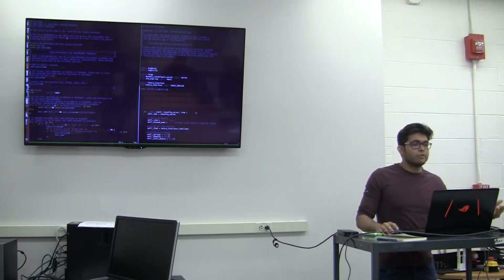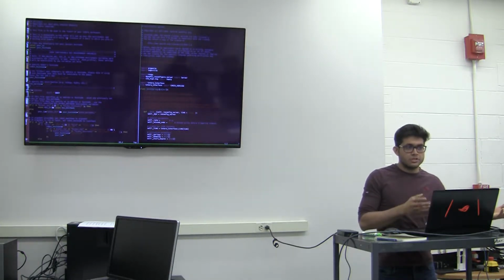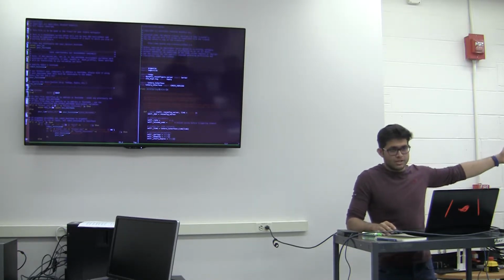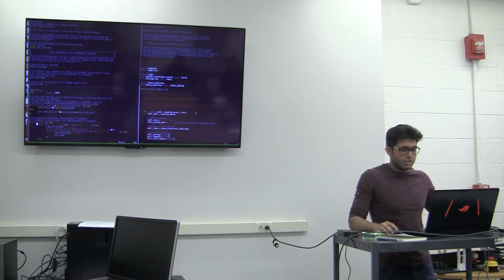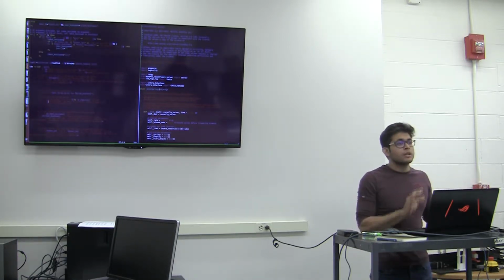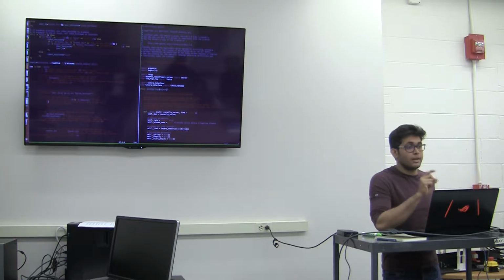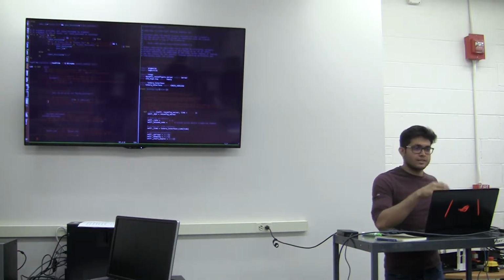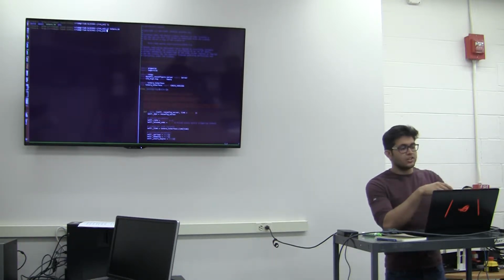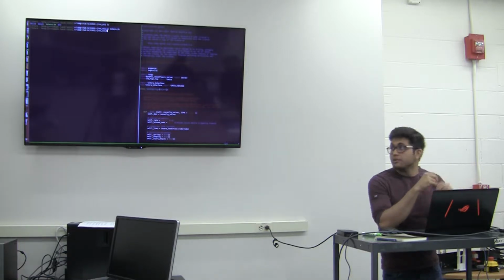You don't have to worry about sourcing your repository again. You don't have to worry about what the IP address or the host name of the robot is. You will directly set up the communication. It will take care of Ethernet communication and make sure everything is working. But this intera.sh is provided by Sawyer. So this is their script that we run every time. Similarly, Baxter has their script that takes us to their workspace. It's their workspace now. So when I go outside, do you see intera.local, the first part here?